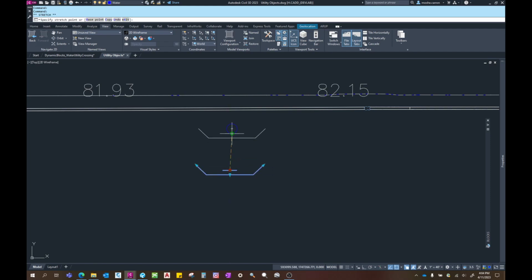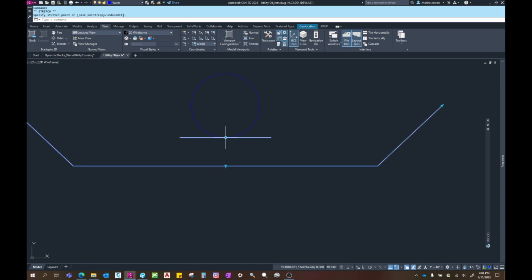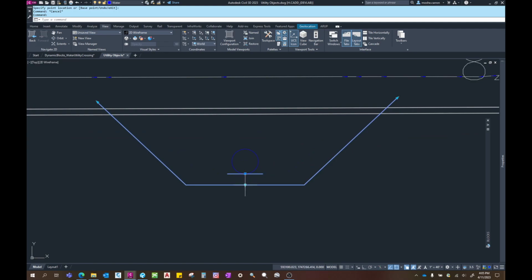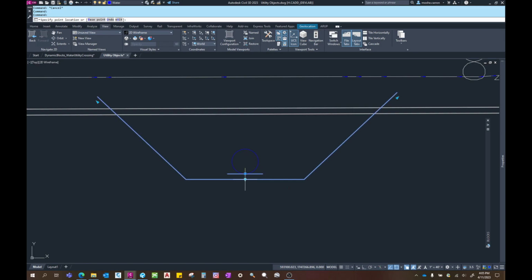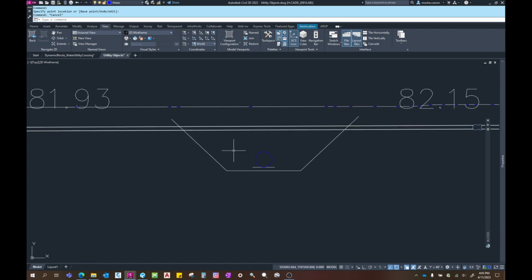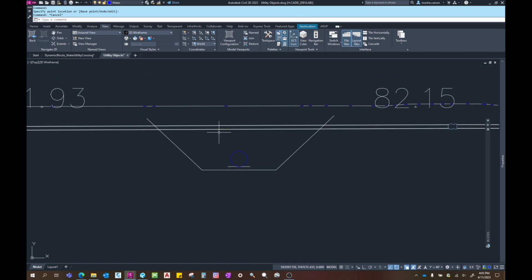I can guide my cursor, snap it to the bottom of the pipe, and extend these leaders to some point that crosses the pressure pipe. Then I have options as well. I can drag this cursor to adjust it from 12 inches to 6 inches, and now I have a perfect guiding line for creating and adjusting my pressure pipe network.